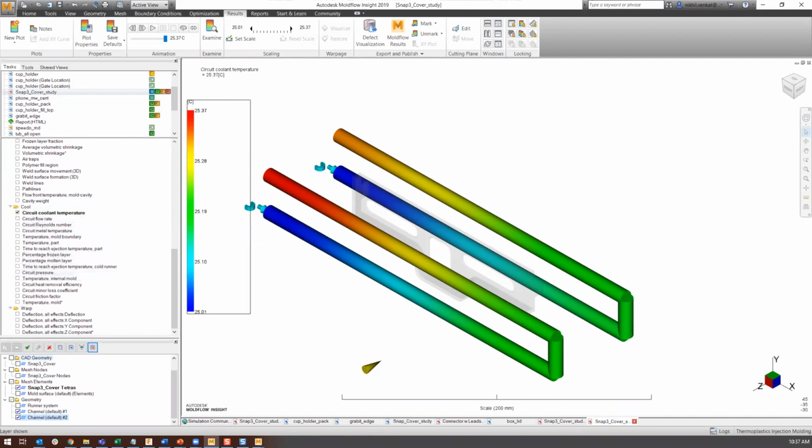And this is detail. If you're a processing engineer, you may want to look at these specific results. To, say, a project engineer, you really care about, is this going to cool apart uniformly so I don't get distortion, and how fast can I get this out of the mold? So, time to reach ejection. But it's compounding. We're adding variation in mold temperature now with this cooling analysis, that's going to have some impact on the final shape and shrinkage. Good example of building detail. Yep, absolutely.